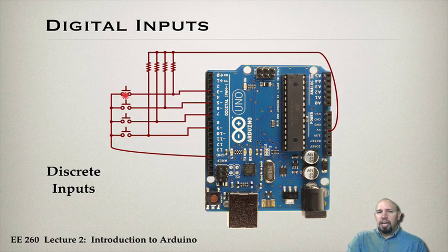Basically, this circuit that involves a switch and a resistor allows this signal to switch between 0 and 5 volts. You can't just do that with the switch itself. If you just try to connect up a switch to an input like this, it doesn't register the kind of voltage that's needed. A digital input needs an input value of either 0 or 5, and this is a simple way of connecting up a switch to give that.